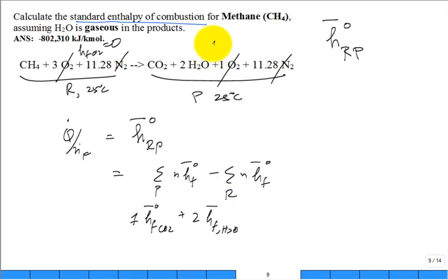And again, there's a choice. Do they come out vapor or gaseous? This problem statement says H2O goes out gaseous. So put a G on there if you really want to emphasize it. And then we have minus the 1 for the fuel, enthalpy of formation of the CH4, and it's going to be gaseous as well. So you just pick up 3 values out of the table.